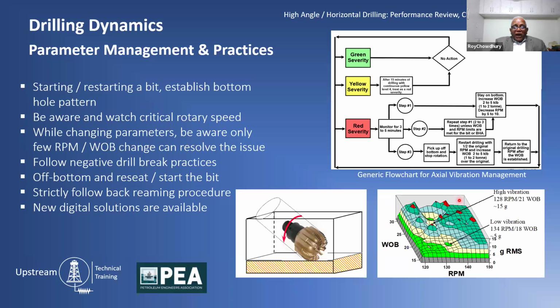Now notice the chart here. This is the simulation window for weight on bit and RPM combination, and what kind of gravity forces, GRMS shocks, the BHA is experiencing.